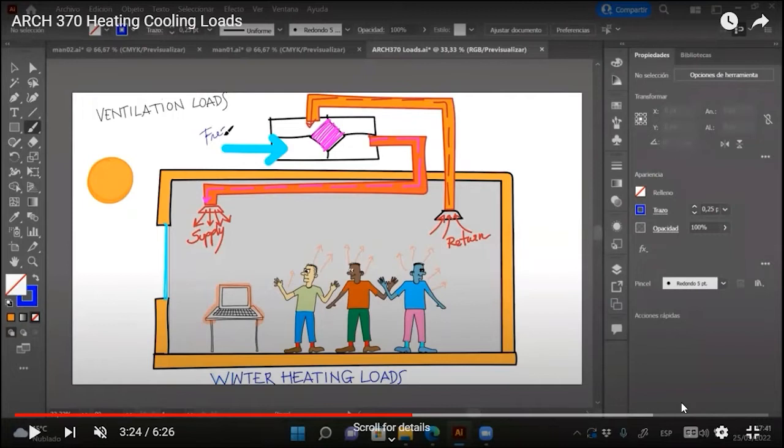It's still outside. But this heat, we transfer part of this heat to the fresh air. So this is 0 Fahrenheit, and this is 70 Fahrenheit. With this heat recovery, we make sure that the air here is 30 Fahrenheit. The 30, we have to keep it up to 70. But "reuse" is not the right word. We recirculate the heat, we transfer that heat, but this air we get rid of. We don't breathe it again. So we have this air and we introduce that air into the room again? We don't do that. Okay.